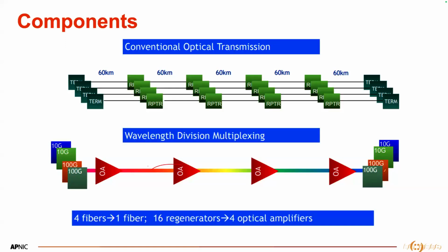Yes, thank you. So there are multiple factors based on requirement. They can modify and plan accordingly. Thank you. Because the OSNR, as you know, is the signal to noise ratio, the power of the signal and the amount of noise. Now, if a lambda has to cross 15 amplifiers, it will have an amount of noise. If another lambda has to cross 40 amplifiers, it will have another amount of noise. You're getting what I'm trying to say?